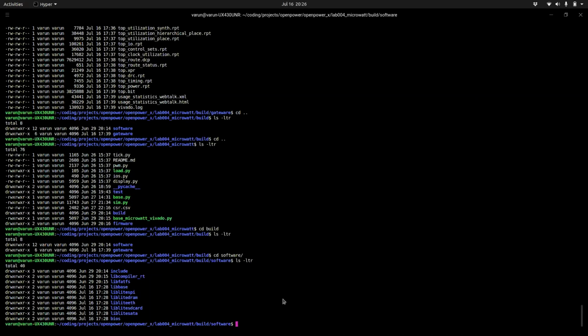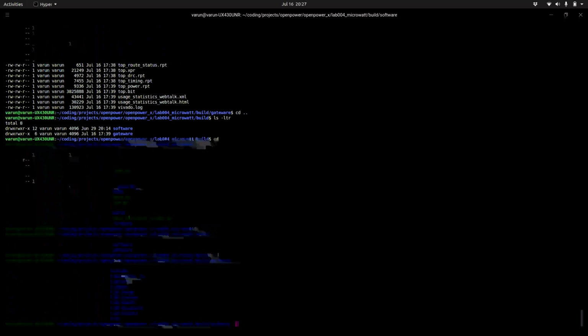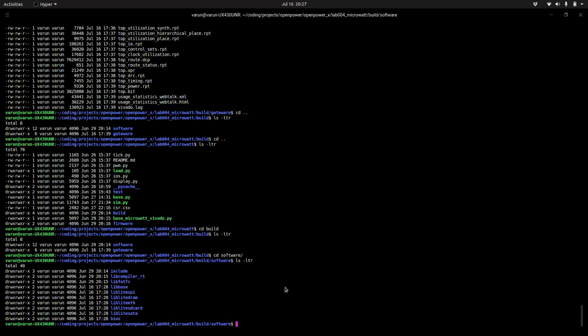So here in this case, you are building the SoC by yourself. The tool itself generates all the headers and the C driver files for you. So you can include those in your project and use those to access the memory mapped registers of the peripherals.